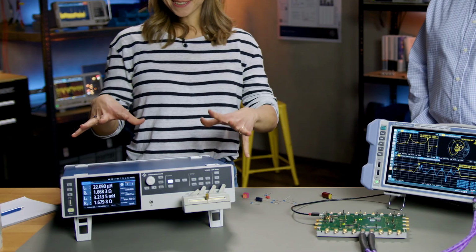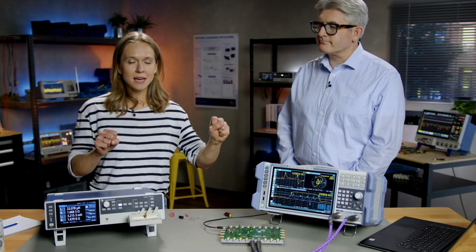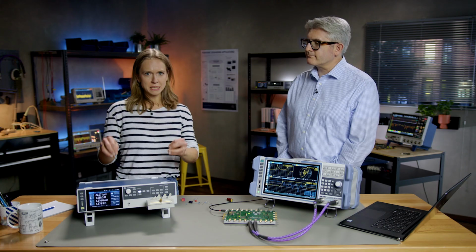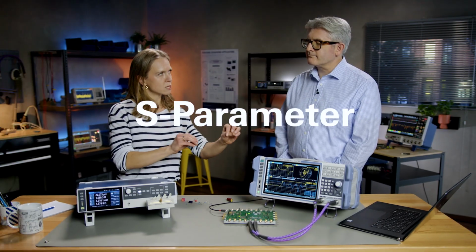So let me get this straight. The choice between an LCR meter and a VNA depends on frequency range of measurements and whether or not I want to measure transmission and reflection characteristics. In other words, LCR meter delivers L, C or R values, and if you need transmission and reflection characteristics, you need to use a VNA with S parameter function. That sums it up very well.